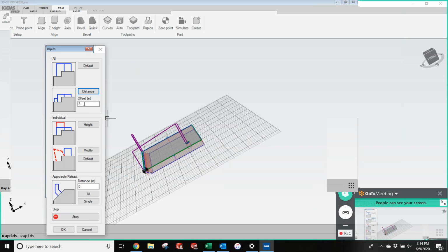My major Z height issue there that I mentioned in one of the emails was during height setter, and Rob, and I think they're working on it still today a little bit. What was happening is, basically I could place the nozzle close to where I thought it should be, and then when it would run height setter, it made the rotational movement to bring the height setter probe to the point of the nozzle before or during the time that it was raising up in Z. So what was happening is, I just happened to be looking at it one time and it swung and missed one of my clamps by maybe a 1/16 of an inch.